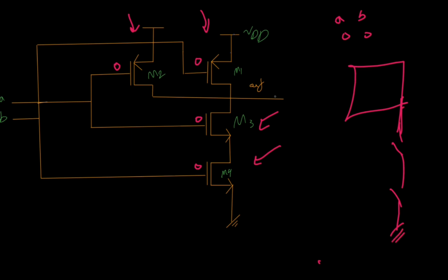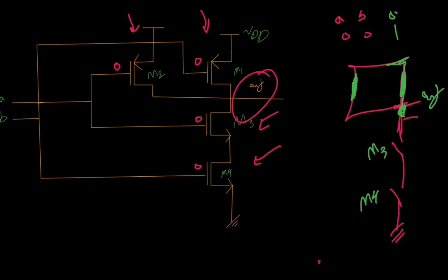We are getting our wires from the out, which obviously is here. We could say this is one transistor. Actually, let me use another color. So this is M1, which is on. This is M2, which also is on, so it is short circuit. We are getting our output from this wire, and these two would obviously be M3 and M4. And if you notice, the out is connected directly to the high voltage or VDD that we call 1. So 0, 0 would give the output as 1.